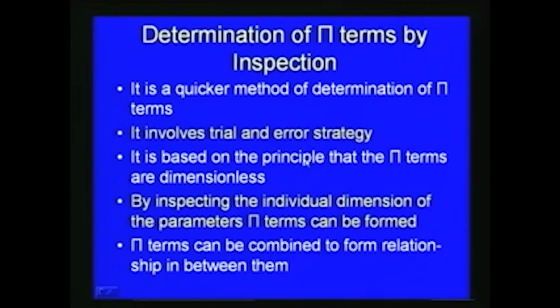Once we decide the repeating variables and the fundamental dimensions, then while checking the particular problem, through inspection or trial and error we can decide how the pi terms are formed or which way we can combine each pi term.